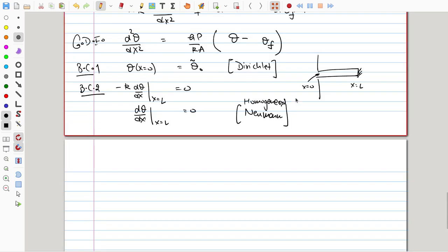Well, now it's actually not that difficult because we have the governing differential equation. Now the governing differential equation is applicable everywhere, just remember that. It's basically obtained from the physical laws of heat conduction and convection. So along any distance along the length of the fin you can apply the equation. Sometimes we get confused, where is it applicable? It's applicable everywhere, including the boundaries actually, but for the boundaries we have boundary conditions which are much more helpful, so we will use those for the boundaries. But this equation is applicable everywhere along the length of the fin.